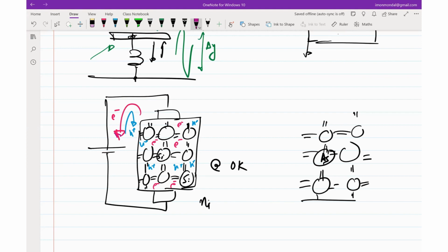This argument only works when it's not as if most of the silicon atoms got replaced. Only some of them got replaced. So if we only observe that arsenic atom which got embedded, which replaced one of the silicon atoms in the lattice, then we're going to have one extra electron which is floating around, because that's the unfulfilled bond.